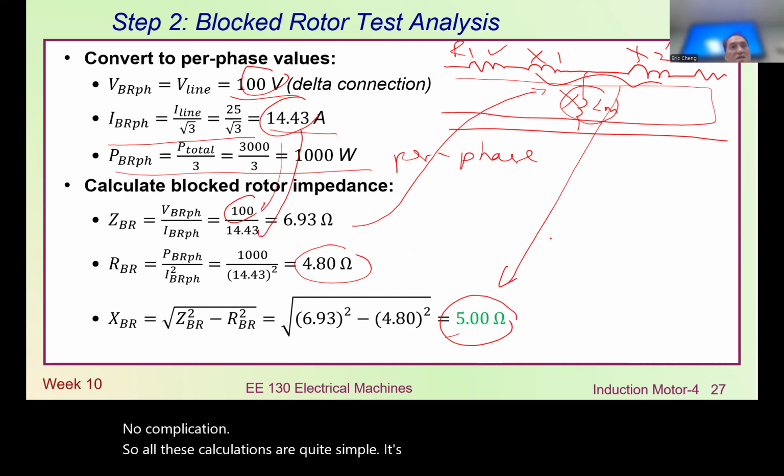The voltage is so small, the B field so small, the core loss may not be significant. We may not be able to estimate the core losses properly. But using the no-load test with full voltage, the core loss will be more significant. We are able to use this measurement to measure the core loss.